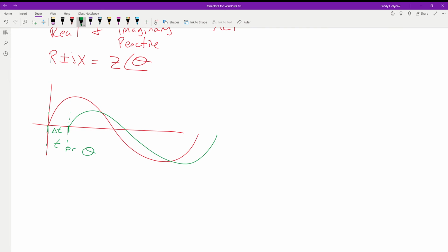How do we determine that angle? With the triangles. Okay, but if we're just looking at it on a graph like on our waveform, how would we figure out what that phase angle is? Cursors, yeah, they would give us the time. So let's say this one came in at 0 microseconds, and this one came in at 16 microseconds. The last part we need is the total period of one waveform. So if this whole waveform is 160 microseconds, we can find out what the phase shift is. How would we do that?